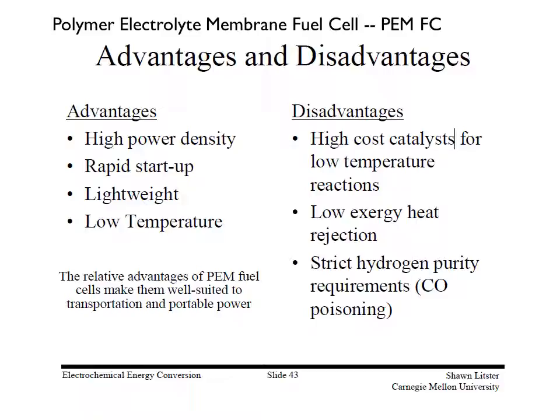Fairly lightweight. A large portion of the fuel cell is actually carbon, if you use carbon plates, or carbon or steel, and polymers, which are also largely carbon-based. So we're not talking about very heavy materials. It's also quite porous, so a lot of it's just air, or fuel and air. And low temperature means a couple things, but the advantage is that we're able to use polymer materials for the electrolyte, and it's fairly easy to seal.